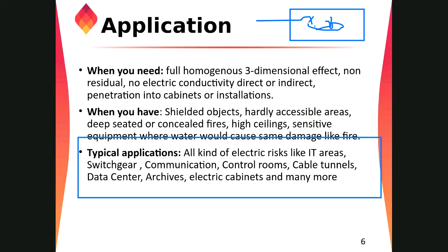The double interlock pre-action system was discussed in the beginning yesterday in the sprinkler system class, right? We need activation from the smoke detector, and we need the activation of the sprinkler system. All together will combine, and only then will there be the discharge.